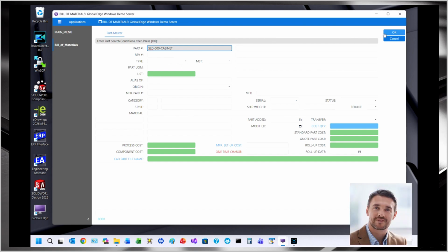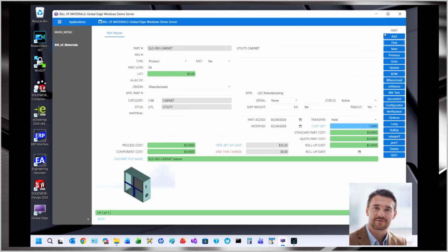The part that was retrieved is referred to as a master configuration part number, or could be referred to as a template part number. For this master configuration part number, configuration rules were defined for each of the configurable parts in the CAD model assembly. This also includes the definition of part numbering rules that are applied to each configured part, including each assembly part number in our demonstration illustration.